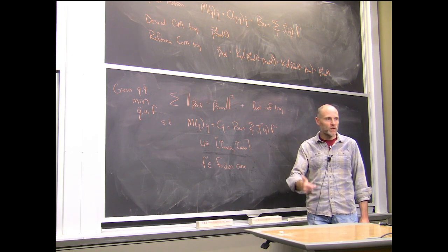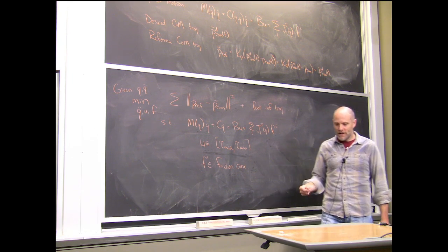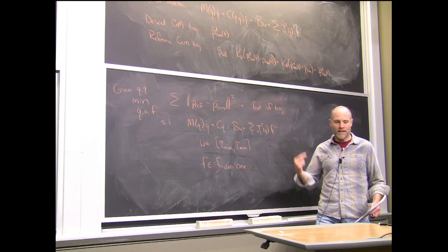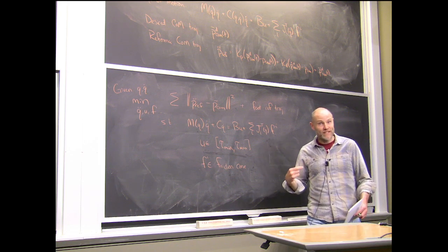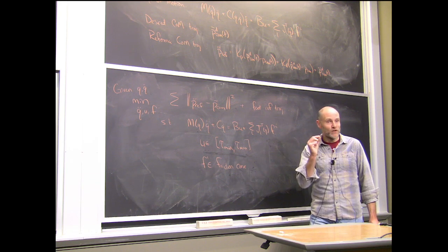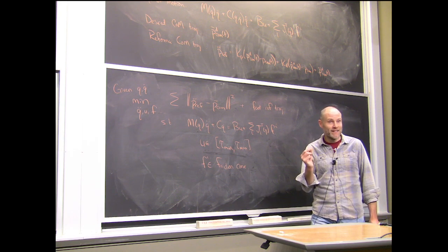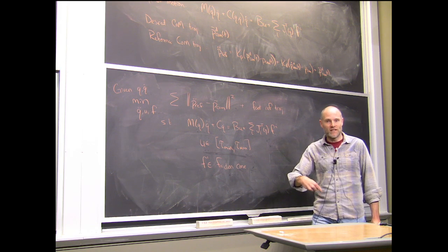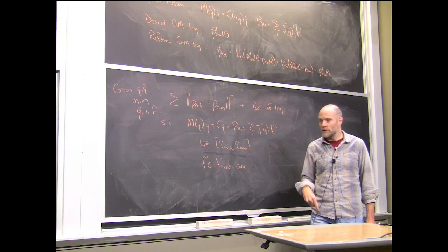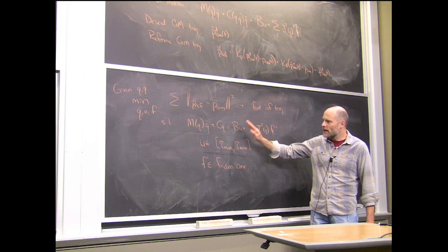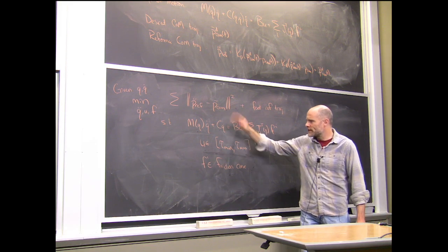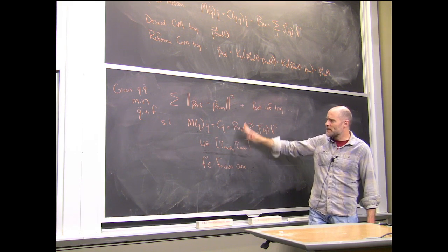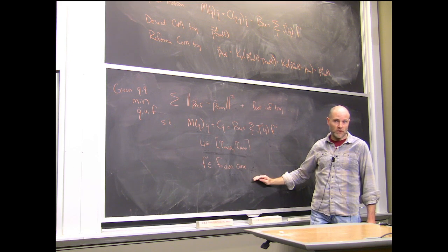So once we got our control rates up very high, then basically the solution you got on the last time step, if your next time step is very soon, then basically not much can happen. And so your last solution is very close to the next solution, and the simple heuristics work very well. This is not exactly it, we solved out U, and we did a couple things to make it a little faster, but this is basically the QP we were solving on Atlas almost all the time.